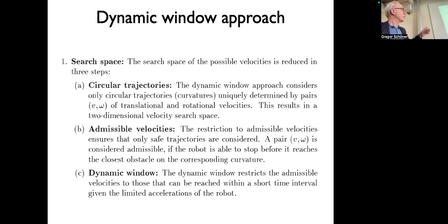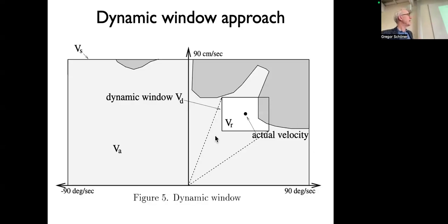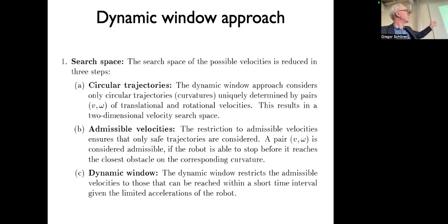And there are some ways of doing that. And the critical idea is that in the end you only evaluate that within a window of your current speeds. So to do this fast, you're not actually considering the entire map. You're only looking at its local window. And there are some other ways to do it. You have a model for how you move, piecewise circular. So a constant turning rate and a constant speed give you a piecewise circular trajectory.